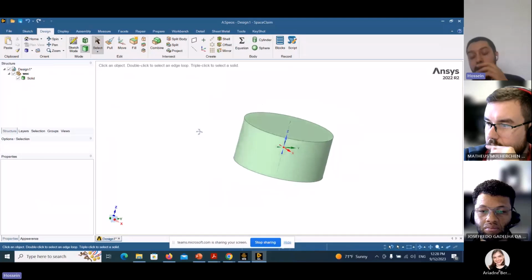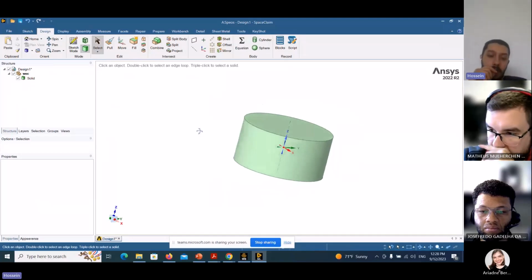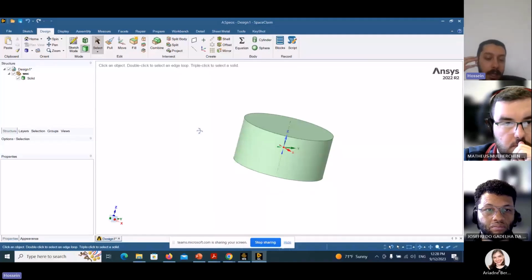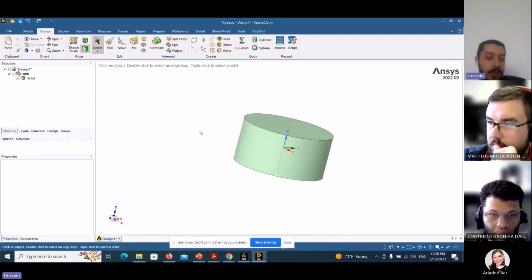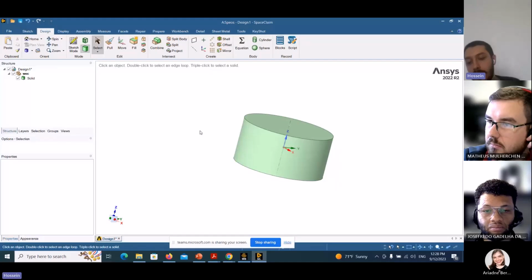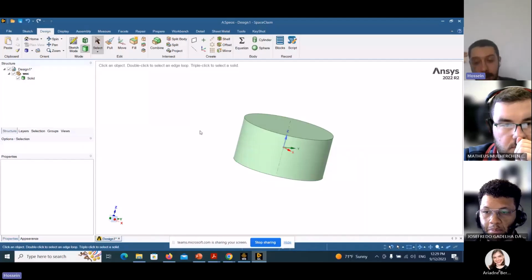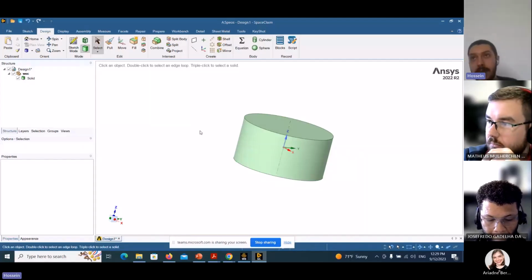As you know, in ANSYS AQWA, the hydrodynamic analysis is based on the diffracted parts, and all of the hydrodynamic coefficients are calculated based on the diffracted parts. And the non-diffracted parts are less important, and they may be needed to analyze the structure.